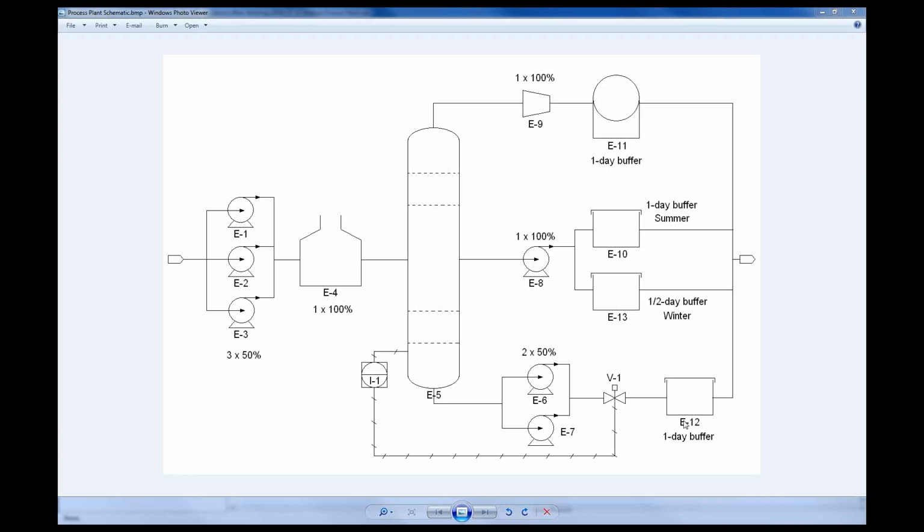The buffers, these are called buffer blocks, but we're just modeling them in our fault tree as just storage tanks. The purpose of them is that in the event something fails up here, like the pump here fails or our input pump fails here, we can continue to operate the downstream equipment by drawing from the storage tank. So we have a little bit of time to repair it before we experience a system outage or a loss of output from the system.